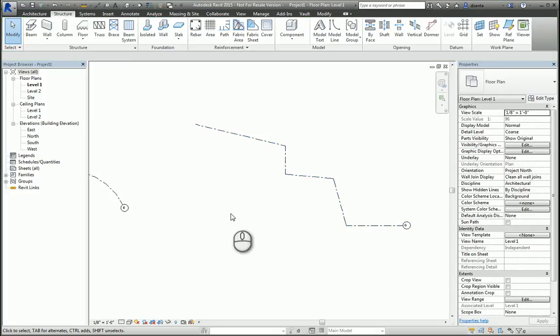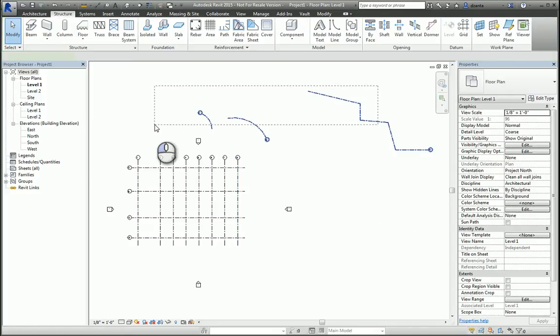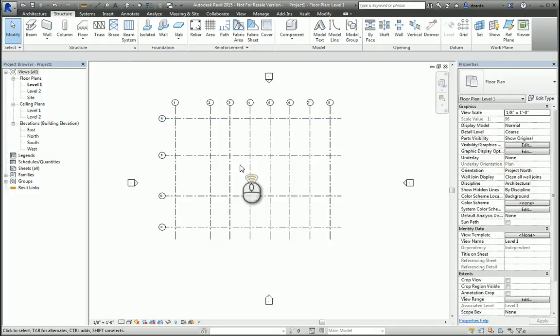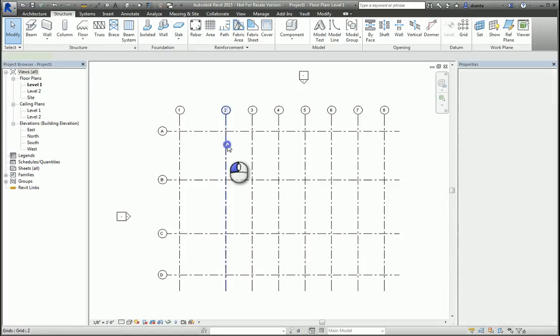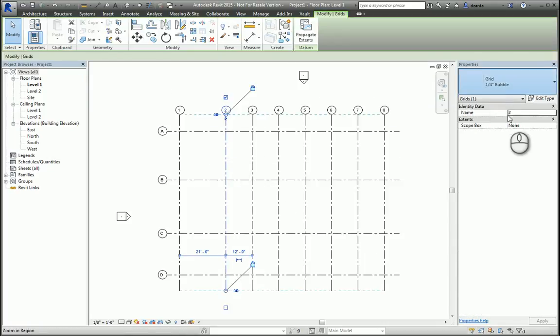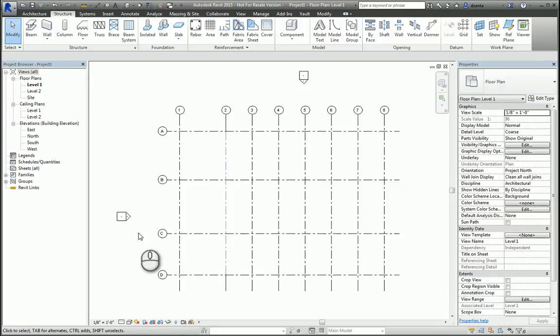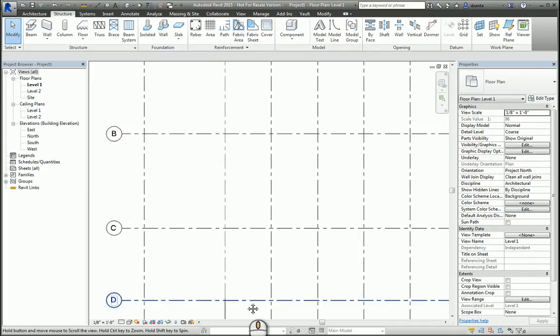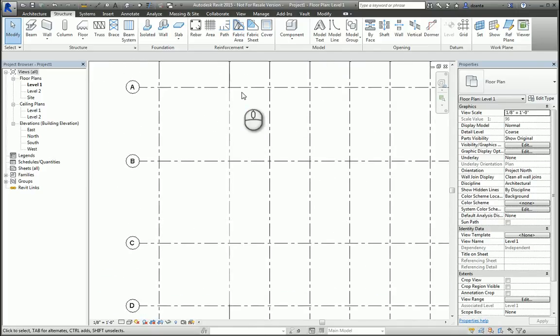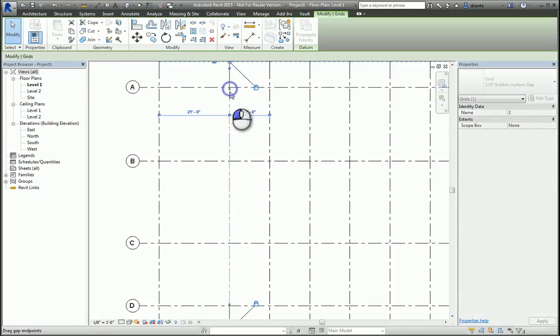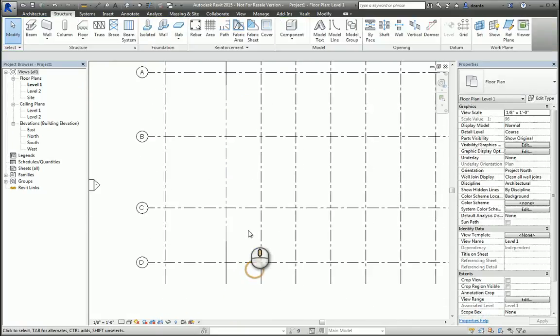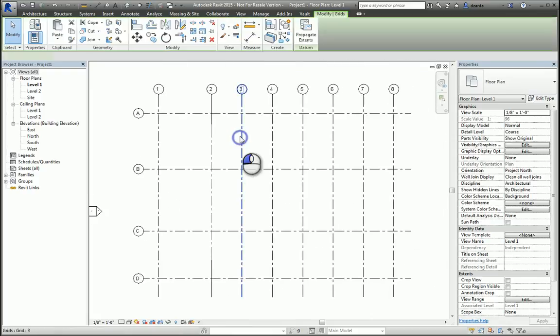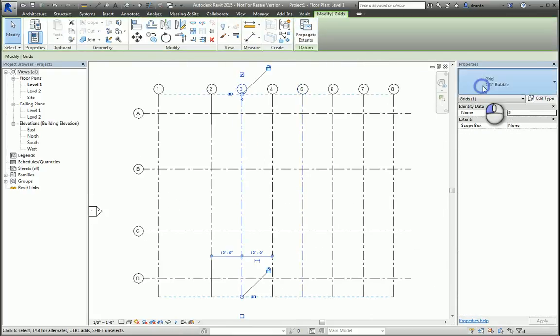Back here in the Grid command, if I select the column grid, I can switch it to the next one, say bubble custom gap. And what you see is that the line work changes to a solid line, very light dashed, and then back to solid line. If you select it, you have these very, very tiny little dots that you can click and drag to change the location and length of the solid and then the beginning of the dashed. You can also select and choose just the bubble gap, and you don't see the dashed line work at all.